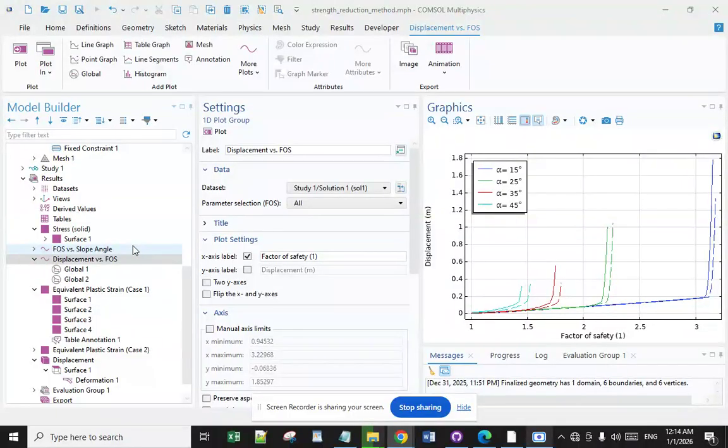For example, components whose failure could result in substantial financial loss, serious injury or death may use a safety factor of 4 or higher, often 10. Non-critical components generally might have a design factor of 2.